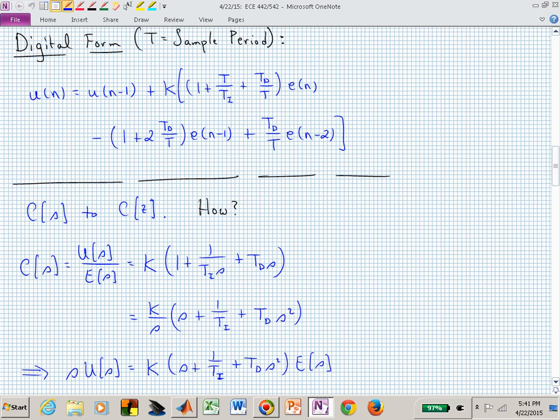Here we're just going to do some algebra with that expression in the time constant form, or in these integral and derivative time forms. First, let's factor out an S out of the denominator of all three terms, and that didn't even exist in the constant term, so we have to put an S in the numerator. We only had one S in the numerator of our derivative piece, so now we have two, and now we don't have any S associated with the direct multiplication of the integral time, or 1 over the integral time.